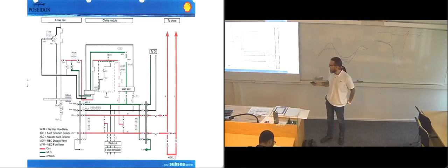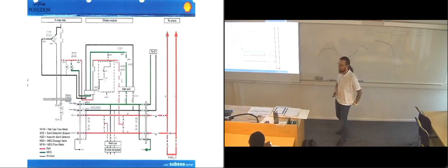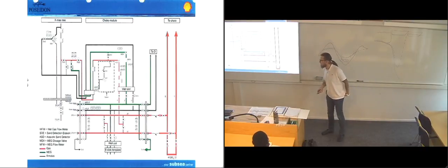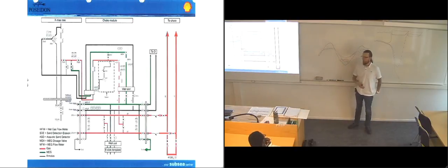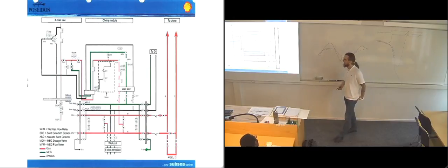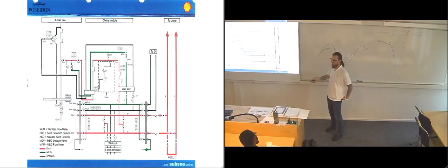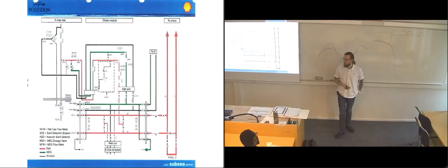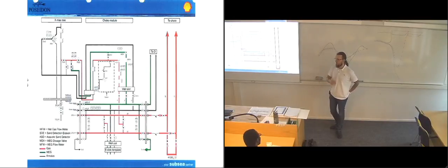We also have some valves and flow meters for the MEG line, the anti-freezing stuff that we are putting into the flow line. Of course we'll need a flow meter, because we want to know that we are actually getting the correct flow out. If there's been a break in the injection line somewhere along the way, then we're not going to get the correct flow here, because some of our flow is going to be going into the sea instead. And we also need a valve, of course, to get it in the correct dosage into the flow line.